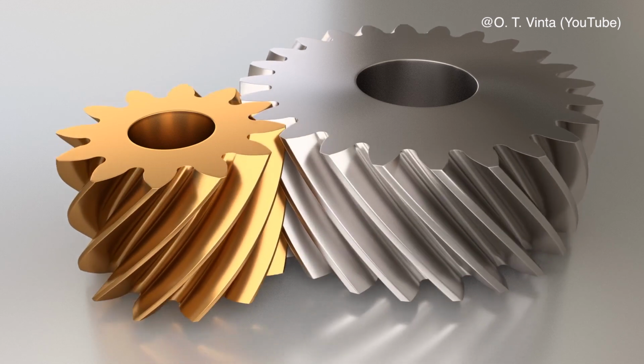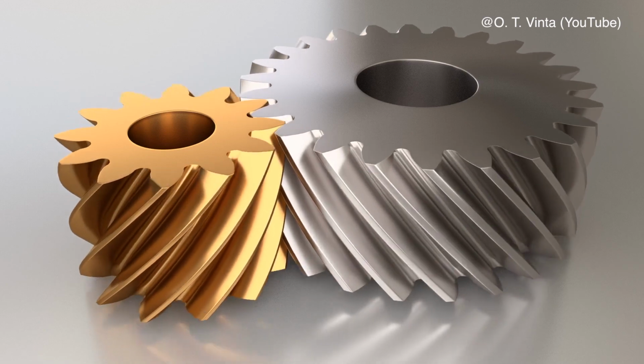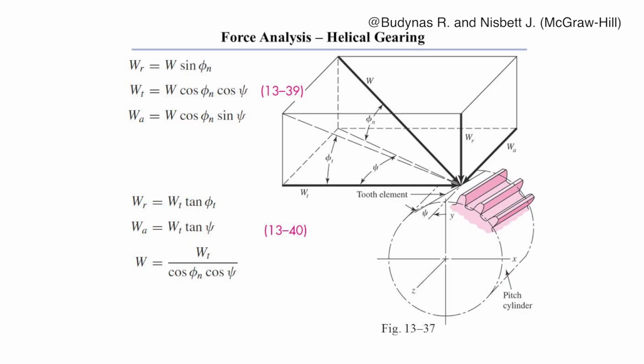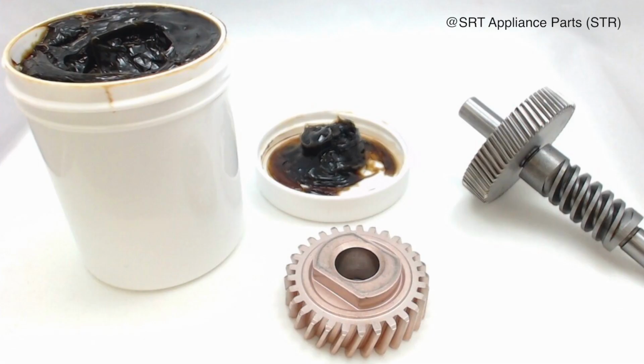This comes at the expense of a thrust along the gear axis, which increases wear, requires plenty of grease, and lowers gear efficiency.